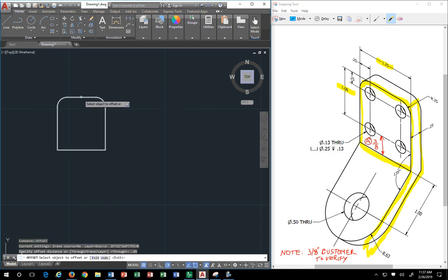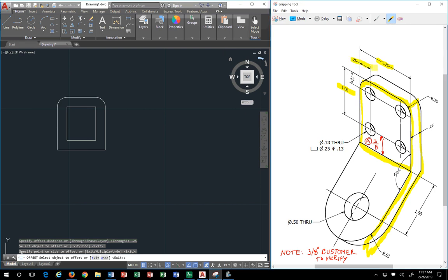So we'll offset in. Now you'll notice I did make an assumption. I used the rectangle command for the outer shape, and then I just did offset by 0.25. And the assumption is that, which is true in this case, it's 0.25 by 0.25. But is this bottom one correct? Nope, because that's supposed to be 3/8. Okay, so keep that in mind. So you do have to explode your rectangle. X enter, because that bottom line is wrong.